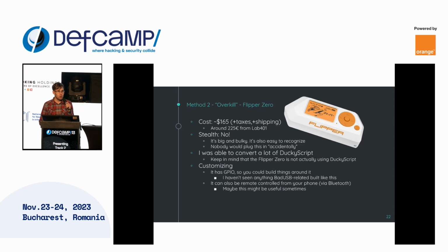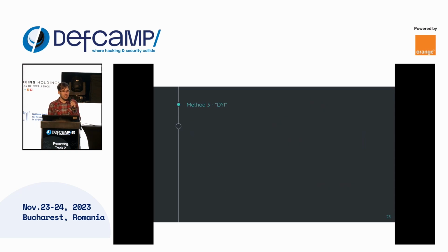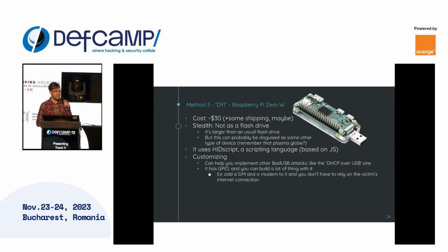Now, you are probably thinking the next one is going to be even more expensive, right? Well, good news, no. The next one is the DIY option. So here I took a Raspberry Pi 0W, W for wireless, and I attached an adapter, a board to it that used some pogo pins. It connected to some data lines and the power pins. And it is now able to connect by using USB-A. It's basically a dongle PC, like an Intel compute stick.